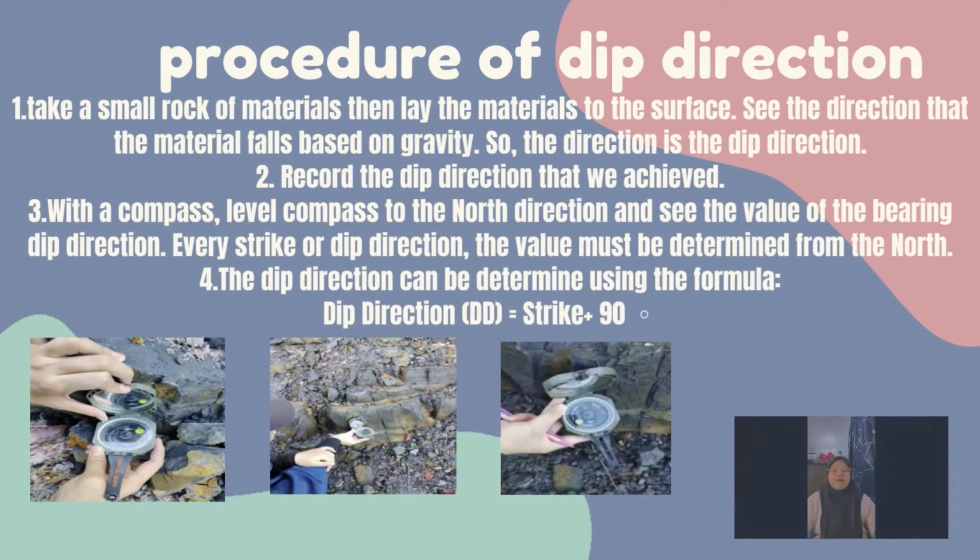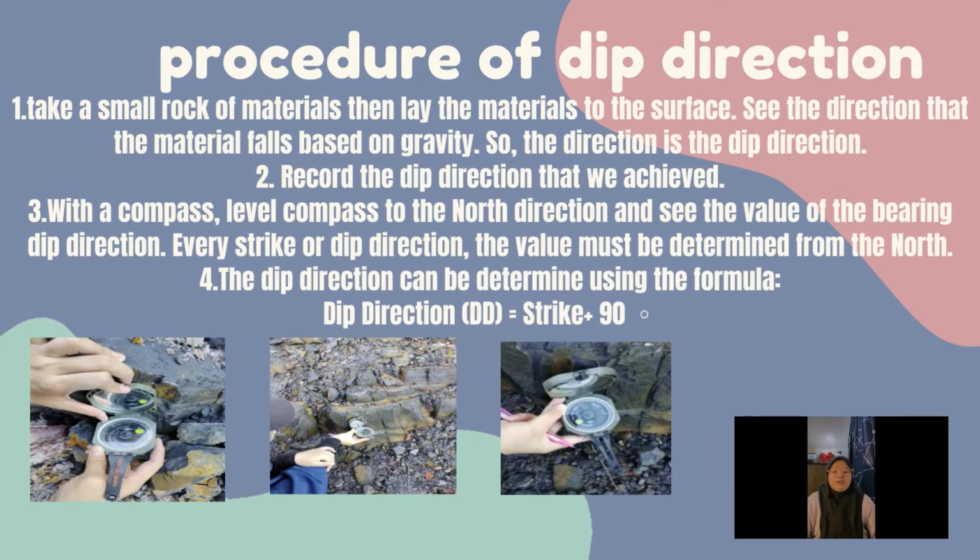The procedure of dip direction. Take a small rock or material, then lay the material on the surface. See the direction that the material falls based on gravity. So that direction is the dip direction. And then record the dip direction that we achieve.